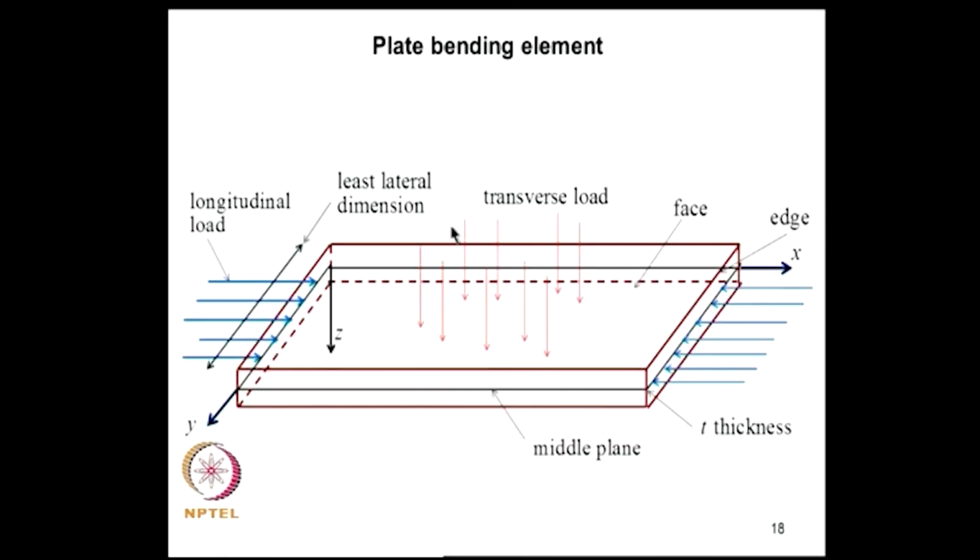Now, in a problem like this, the loads can act transverse to the middle plane or in line with the middle plane. The problem of loads acting in line with the middle plane can be tackled using plane stress models, whereas the question now is how to treat the analysis of this type of structure under transverse load, that is known as plate action.